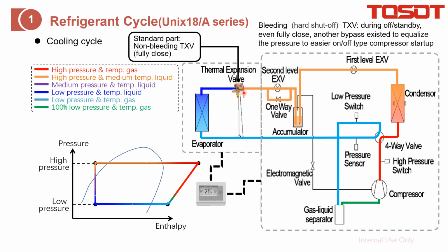That's fine, it's okay. But what is the consequence? It is that the pressure, which is at the left and right for this case, cannot equalize, which is difficult for the compressor's next start up, especially for the on-off. And at that time, during the startup, the on-off compressor, the current will become much higher, and it always requires special equipment to lower this current.